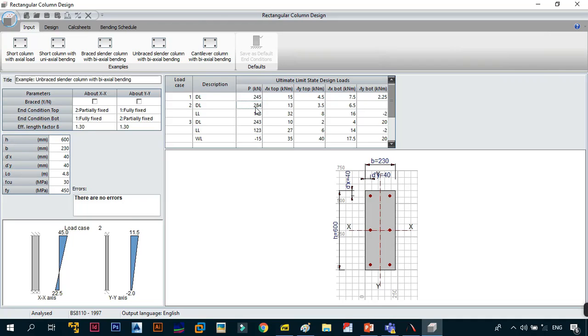So in case where you want to design for large loads, it doesn't make sense to make a concrete column for tension. Now, having said this, the next thing that we just need to look at under this is the moment. So you can enter a moment for the top and the bottom as well. That is in the Y and the X. Each have their own for the top and for the bottom.